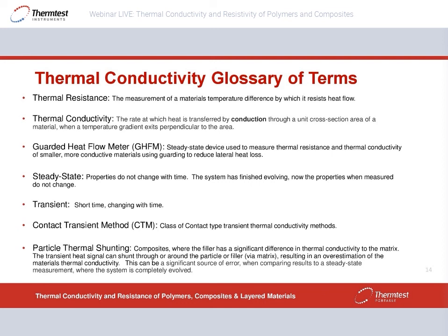But again, if you have a limited budget and you're looking to make some measurements and are okay preparing several thicknesses, there's a possibility you could do it with this method using the multiple thickness approach. That's the way of backing out the effects of contact resistance. It would mean you still have to account for anisotropy in the other direction. This method is guarded.